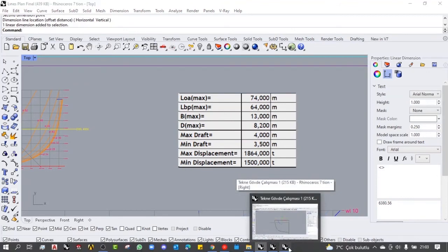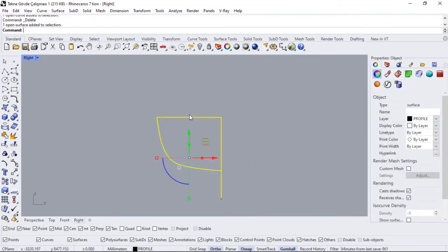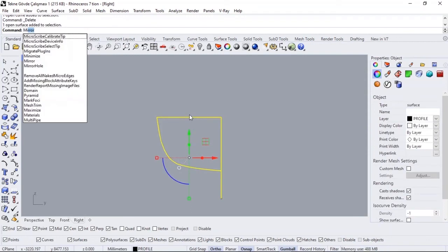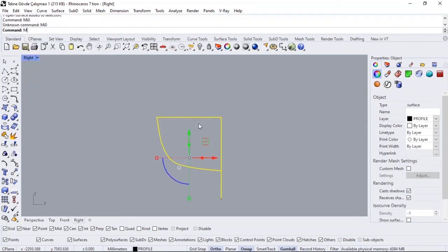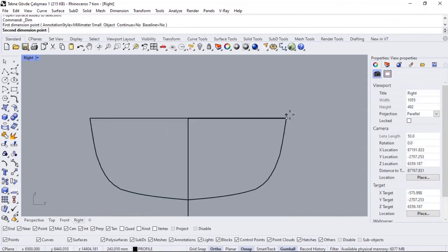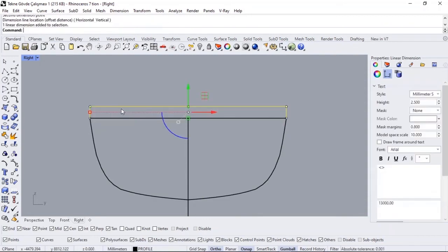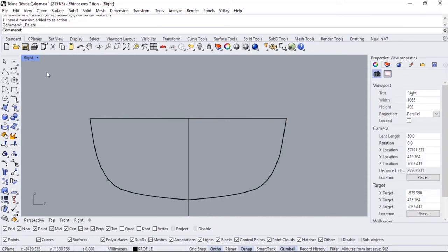Let's go back to the body again. I want to repeat it again. I've selected the body now. We currently have half the hull. I enter the mirror command. I choose 0. I get the symmetry by swiping it up. That was the whole boat. Since we are talking about half of it, I set 6.5 meters to the width. So if you measure it all, the width will now be 13 meters at the top. Totally 13 meters. I choose delete.